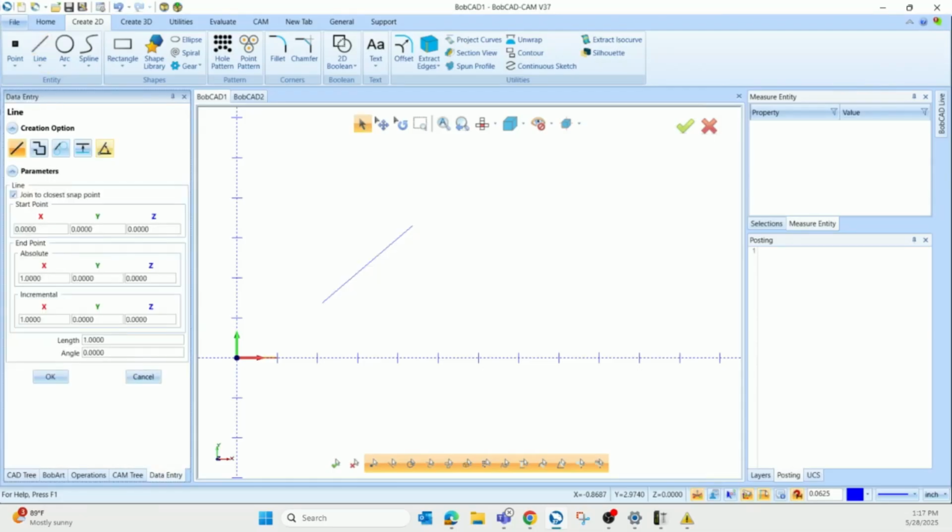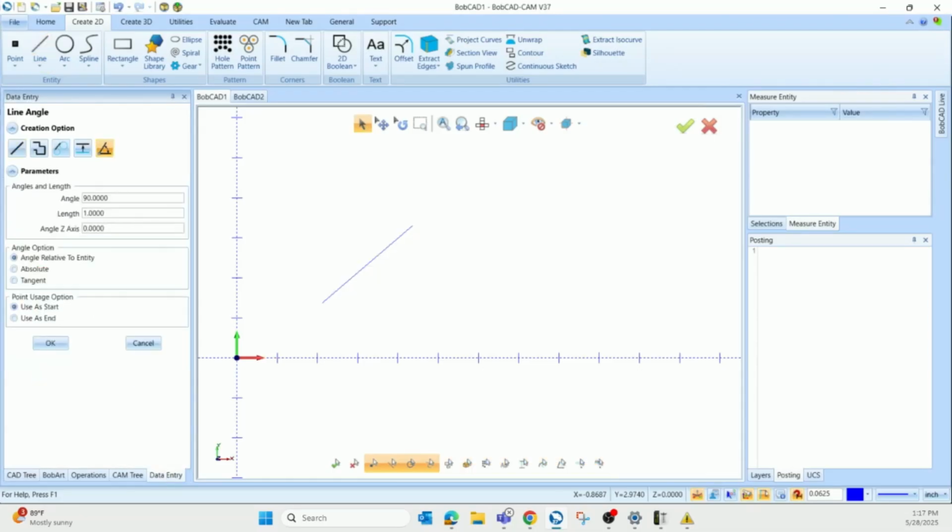And then I'm going to go to line angle. Once you get the hang of it, it's going to be really useful because let's say it's 90 degrees, but I always want it to be going up 90 degrees. I could click on absolute right here. And so when I hover over this endpoint of the line, it's always going to be going upward at the 90-degree location in a trigonometry sense, from the 0 degree being the 3 o'clock position. Or if I hover over the endpoint on the other side of the line, it's still going to be going up at that 90-degree position.